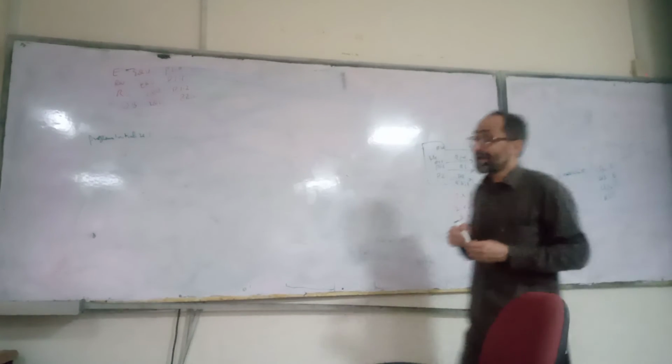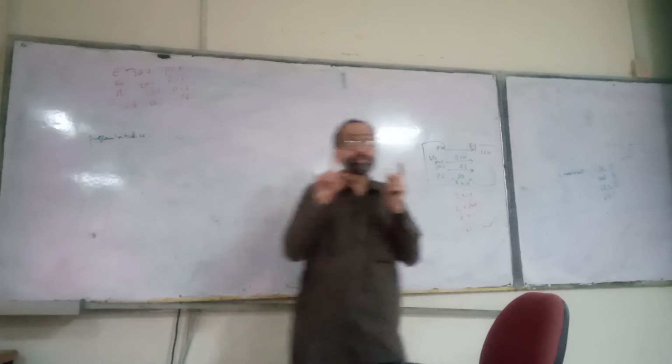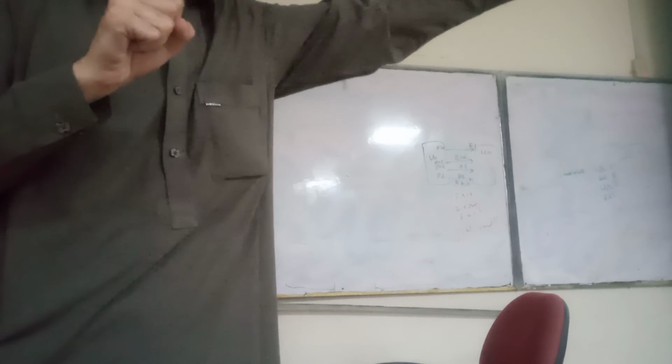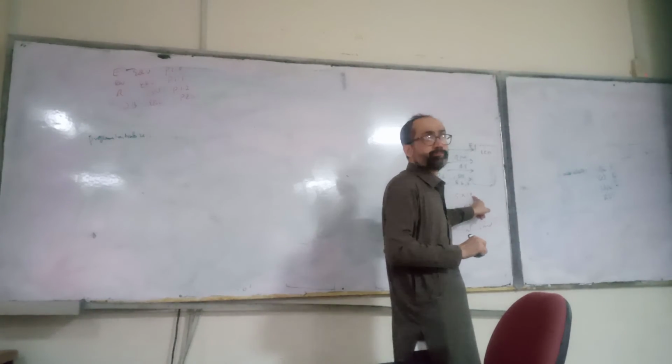Okay, this LCD will not latch the data until it receives a pulse. Okay, now what do we want to do? We want to initialize the program. We want to have a 5 cross 7 standard display.